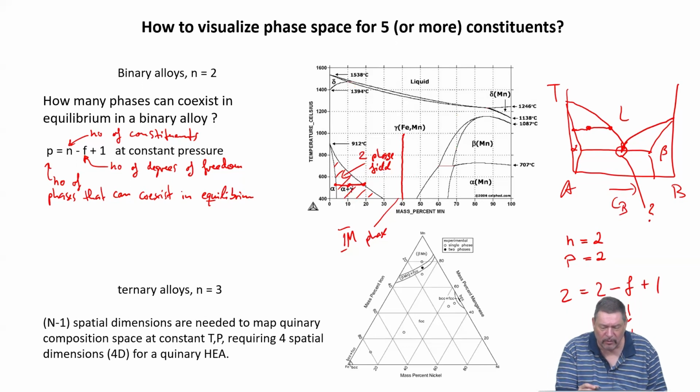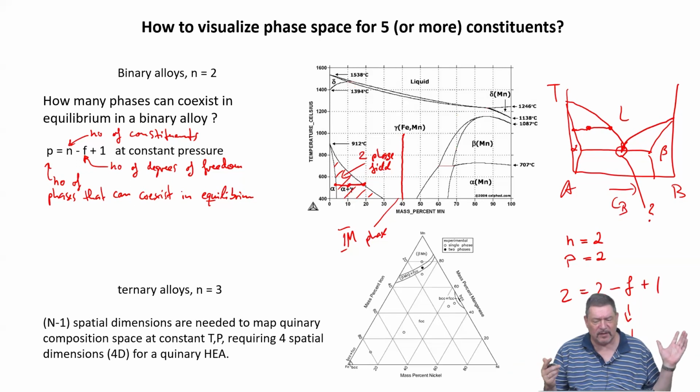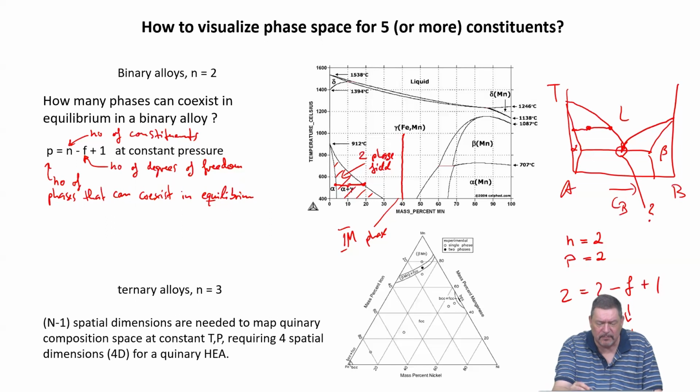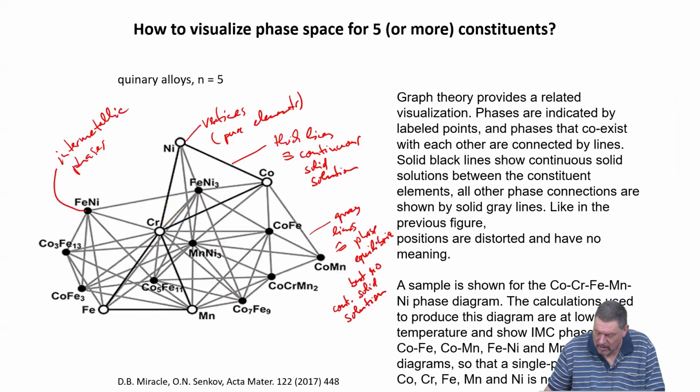If you change the nominal composition along the line, then you will change just the abundance of one or the other phase, but the phases stay the same. And this is meant now with this connecting line. So this line connects alpha and solid solution, and this one here connects cobalt manganese with cobalt.